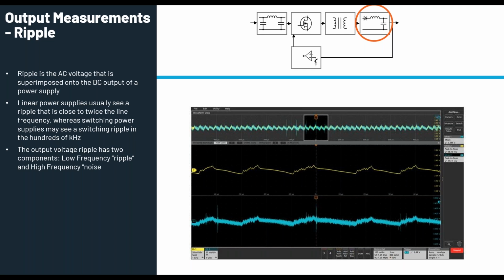There are various methods to do this, and we also have a specialized probe to do that, called the power rail probe. That's the best probe, which has very good sensitivity, and you can look at the microvolt range of ripple, which is very common in today's switching devices.